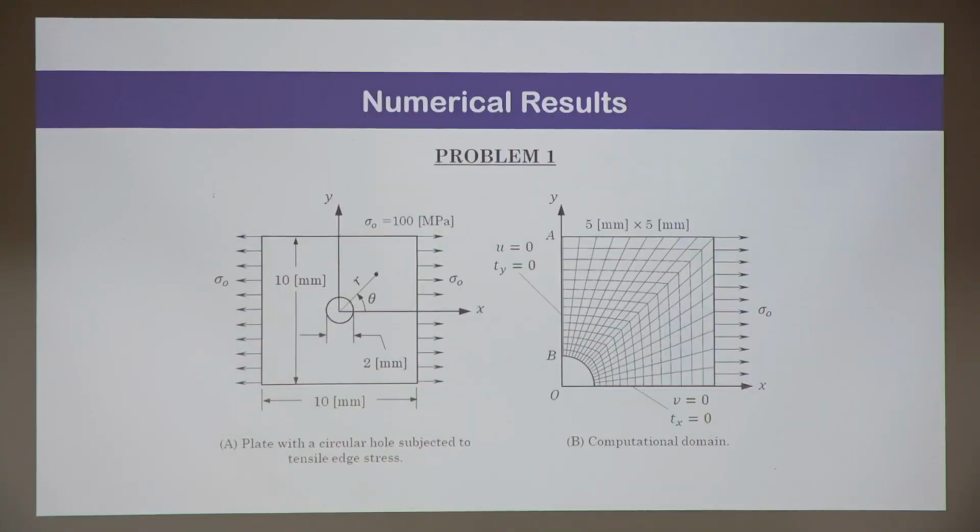This is the first problem. Plate with a hole, standard. By the way, it's not an unsolved problem, just to compare. And this particular problem has an analytical solution, not an exact solution. Remember, there is a difference between the phrases analytical solution and exact. Analytical means you didn't use any computational method. Okay, you found some way to come up with the solution using the techniques of mathematics. But exact solution means you really solve the equations exactly. So with analytical, you may be doing some approximation to get the analytical solution.